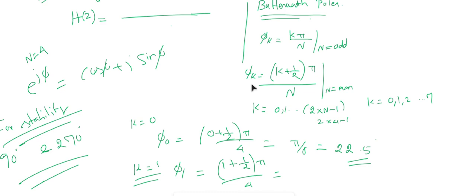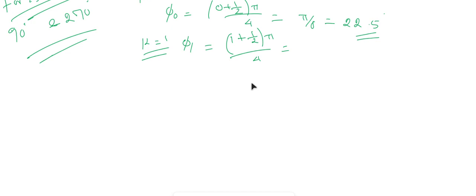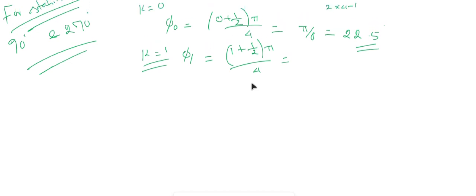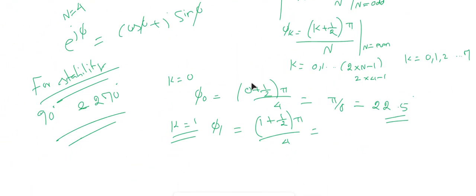In order to find the order of the filter, the specification may be given in different ways. So we can use either one of the formulas with the proper passband edge frequency, stopband edge frequency, cutoff frequency, and passband ripples and stopband ripples. With that we can design the IIR filter. Finally, once we find the feedback coefficients of the IIR filter, we can realize the system in direct form 2, or you can realize the system in direct form 1.